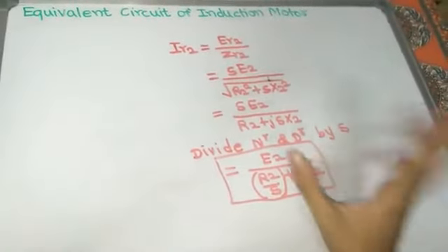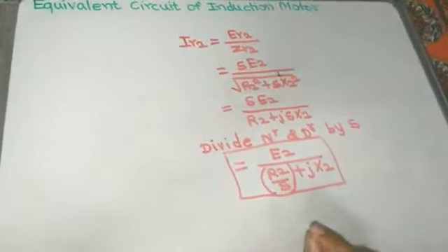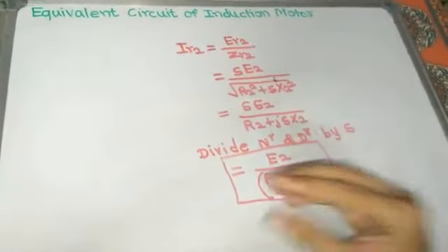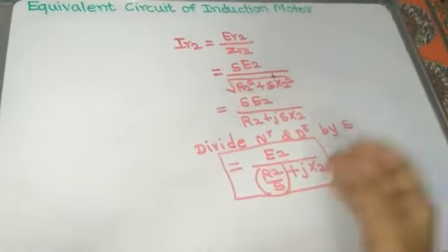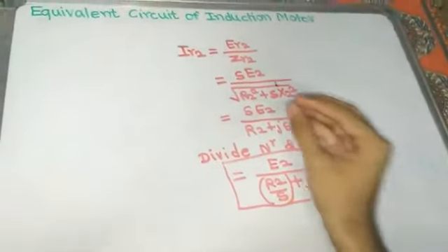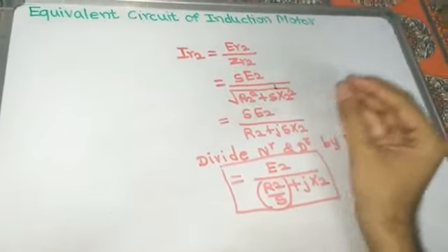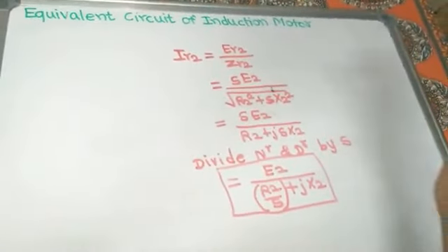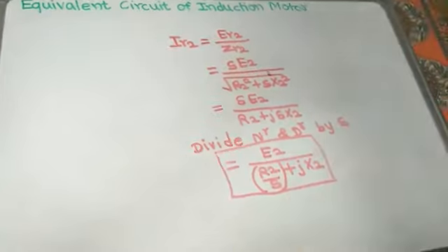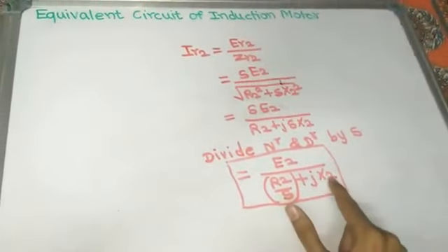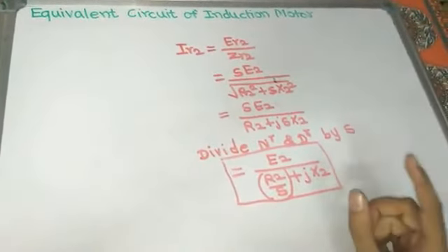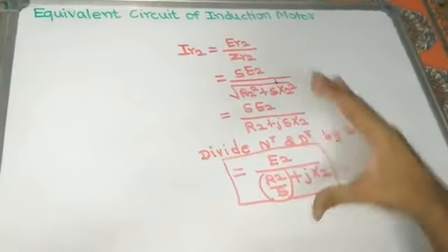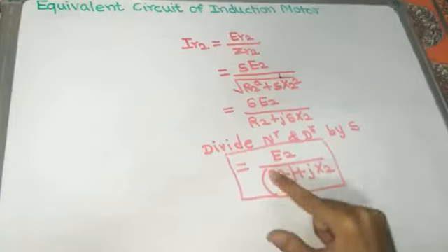Actually they do depend on slip, and the rotor resistance per phase is actually not dependent on slip, but we make everything reverse here to draw the equivalent circuit of the three-phase induction motor, which is similar to a transformer, by making the frequency equal. So see here, if X2 is now not dependent on slip, we remove the slip, and only here slip is applied by making some proper arrangement.